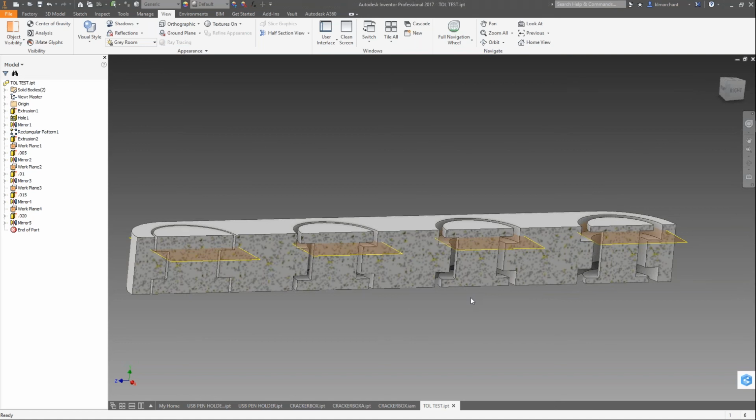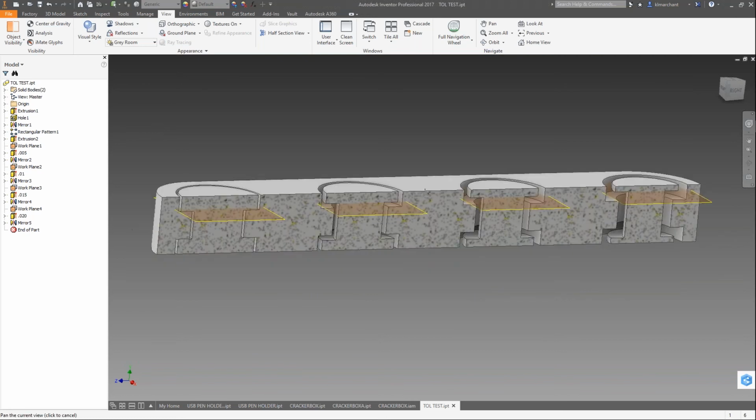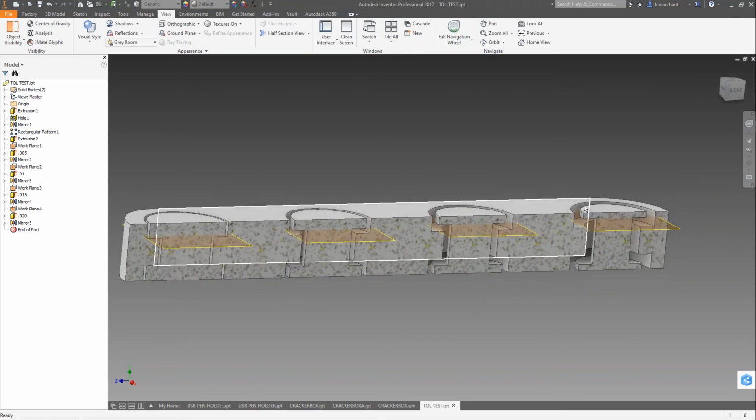And so it allows me to judge if I need to print an assembly, because the way that CJP works, using a wax support system, we then melt that support system out, which frees up this geometry in there. And so even though our assembly may have this much space or that much space in it, we have to know the technology we're going to use to be able to print that and actually have those parts movable in reality. And part of that revolves around the technology we're using.